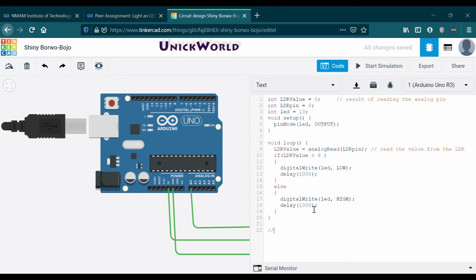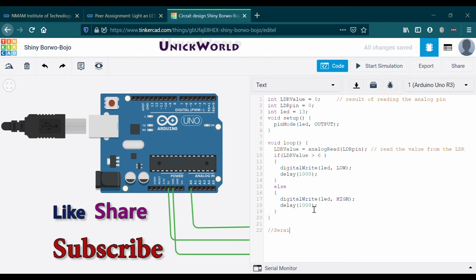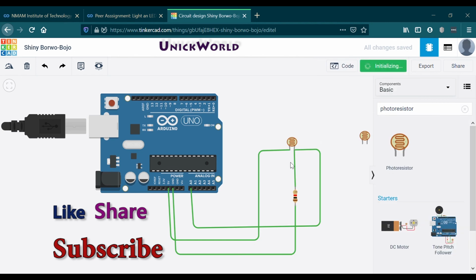But you could ask me how we got it. Maybe it should be 0 or 1, or 0 or 255. But how on earth did you get this value? How do you know that? So no, I haven't got it already. You can use a pre-test, as I may call it, using the serial print function. You can get those values, a minimum of 6 and a maximum somewhere around 800. So this is a feature offered by Tinkercad.